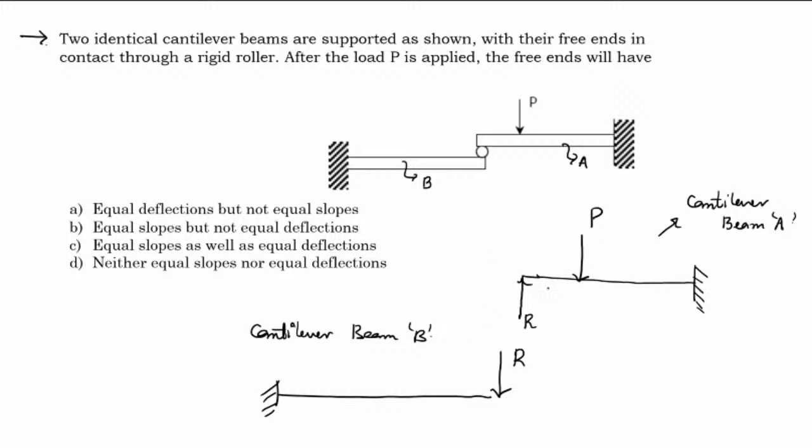Now, if these two beams are required to be in contact, then both should have the same deflection. It is compulsory for us to maintain the contact, so both should have the same deflection.